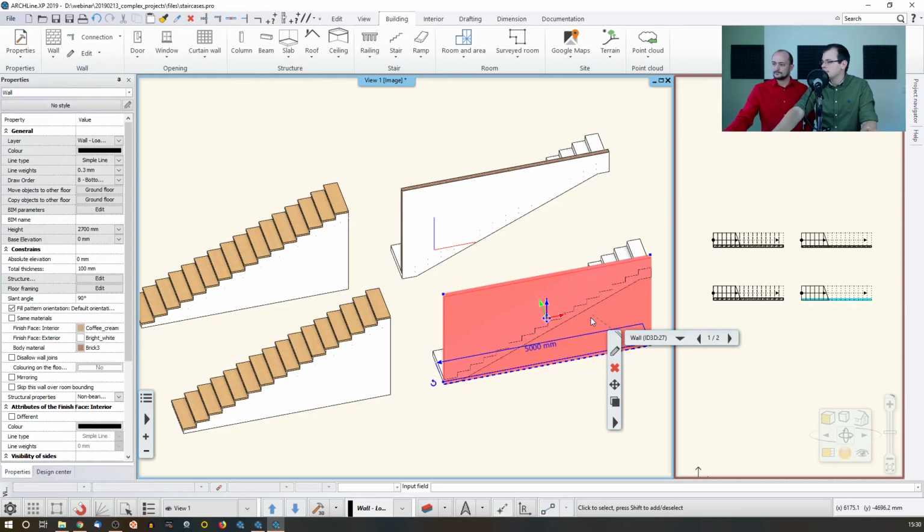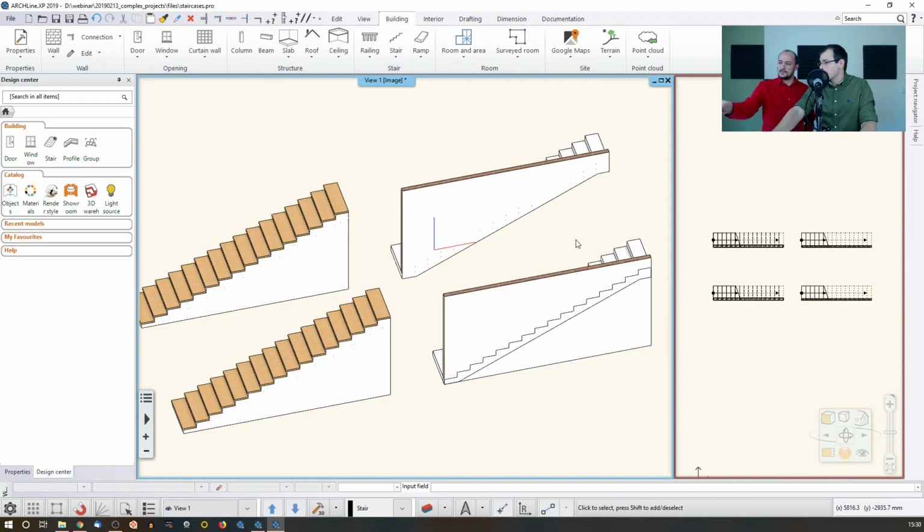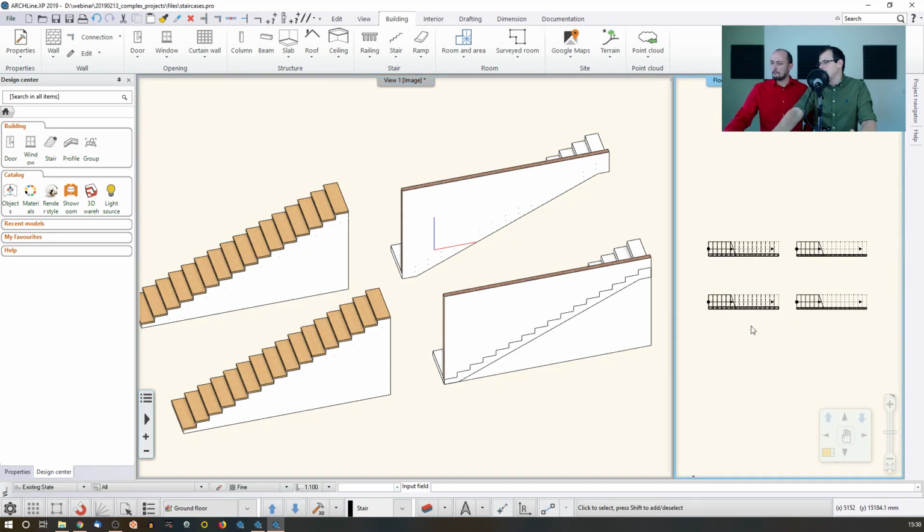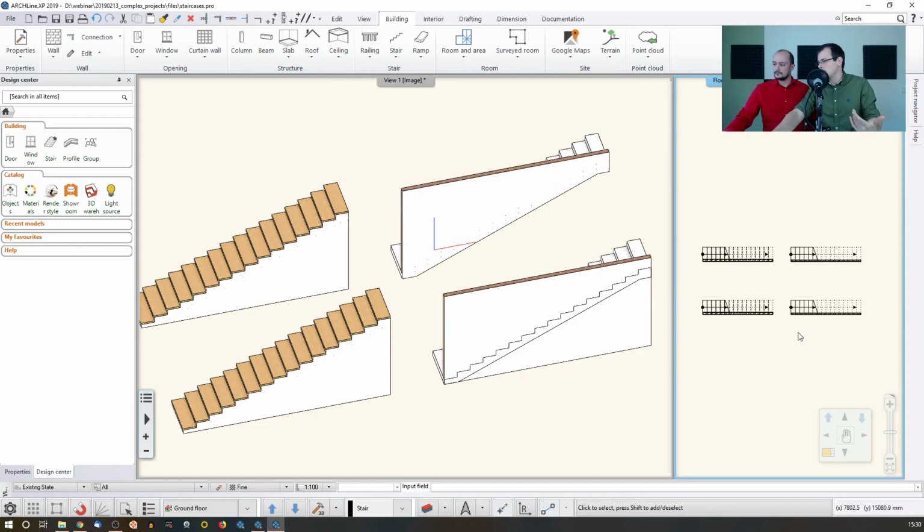But the right-hand side is a bit different story, because I cannot just turn on the same setting and it solves. No, because then it would cut at the bottom; it always cuts from the top. That's right. So we have to find a way to give a frontal profile to this wall, which tracks this. Obviously, I could open up the frontal profile settings and try to offset the nodes until I meet the staircase. But here's the thing: if the staircase is curved, for instance, this would be very difficult to do and time-consuming. So this is one of those scenarios when an automated tool helps you with a complex situation.